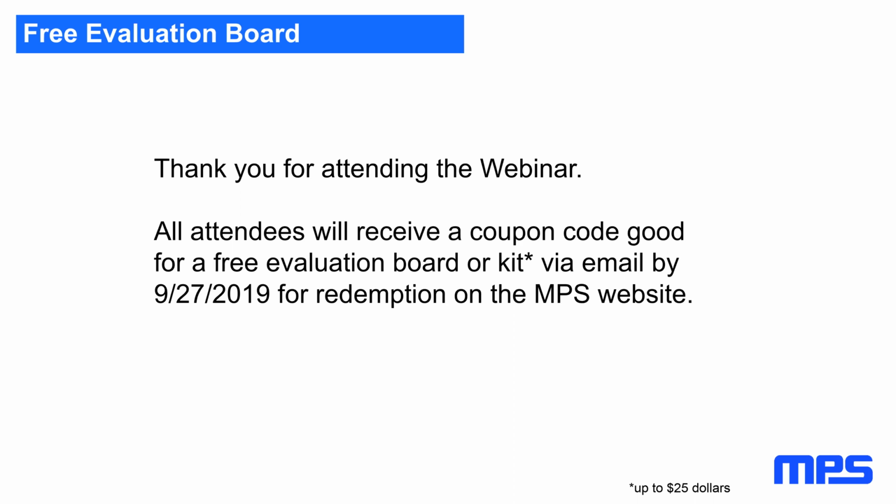So your power supply input and maybe output is not the only connection you have to ground. You also have other bus signals and whatever IOs. As soon as you have that, you can't use a common mode choke anymore, because a common mode choke will also start to isolate the ground of your power supply. So if you can allow your ground to be isolated, a common mode choke is a very good solution.